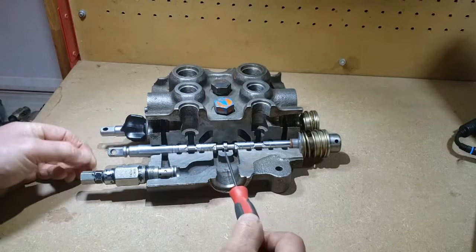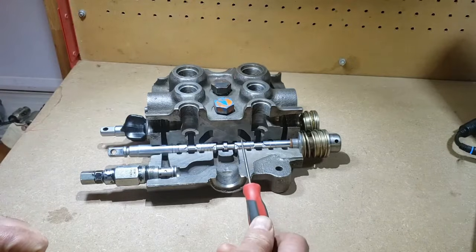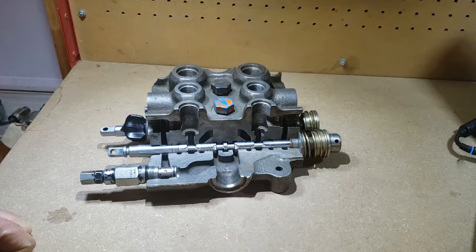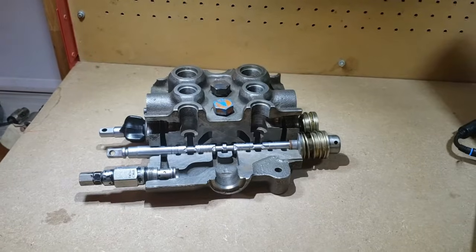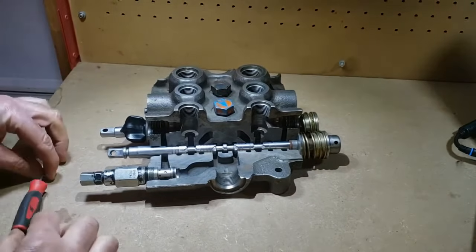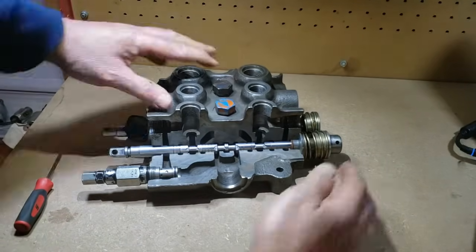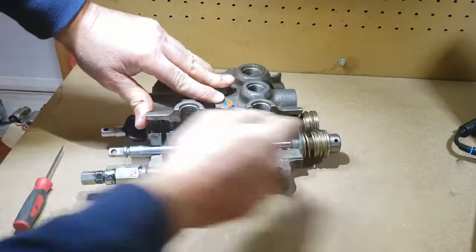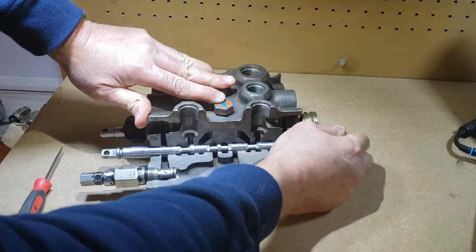So when the spool's in the hold position, oil goes straight through and then to the cooler, filter, tank. So there might be maybe 100 psi of back pressure because of the cooler and filter. Depends on the oil temperature and viscosity. And then the lift spool is a 4-position directional control valve spool. If I push the valve this way, pull it out with the linkage, that is the raise position.